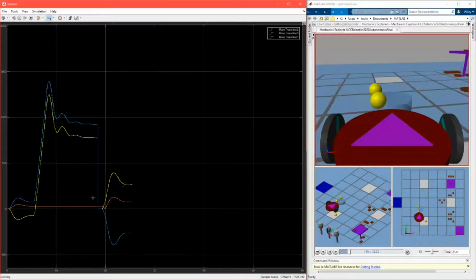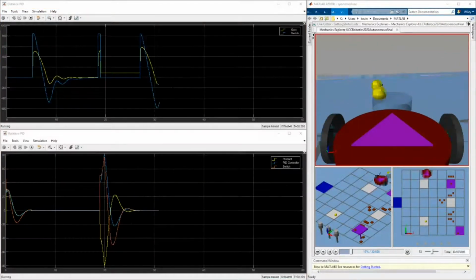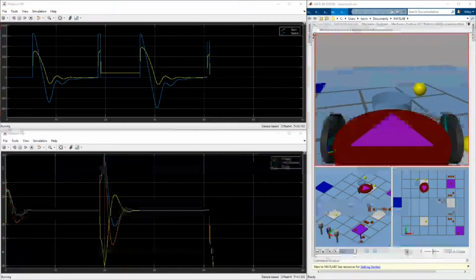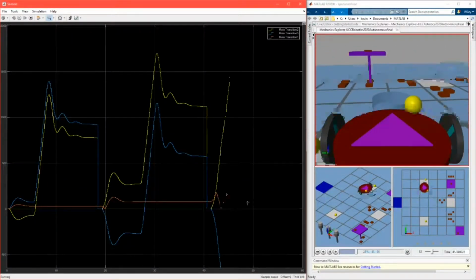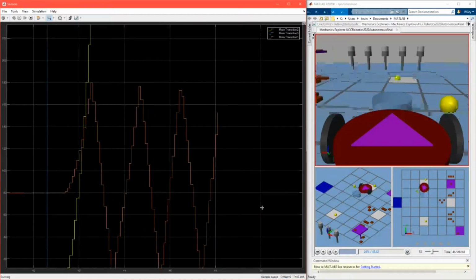We can see the rotation and distance PID input and output, while they attempt to reach a stable state. As the distance to the target decreases, so does the motor output. This system is nearly perfect except for one major flaw in sensor limitations. Specifically, the angle sensor is hard-coded to not go below 0 or above 180, and instead flips directions, making proper rotation impossible past 180 degrees.